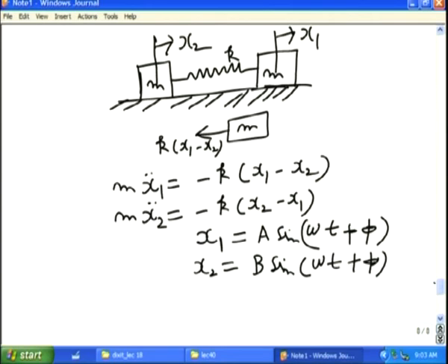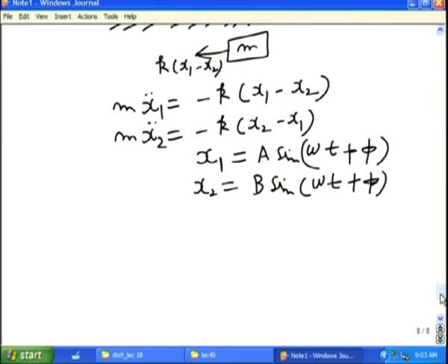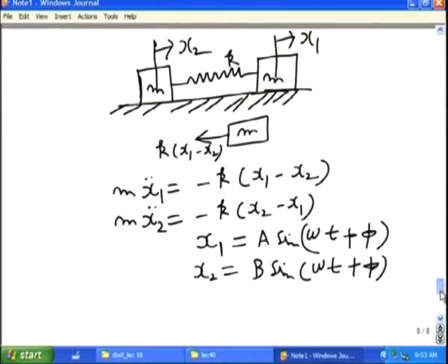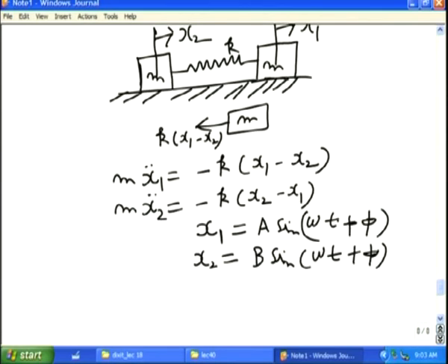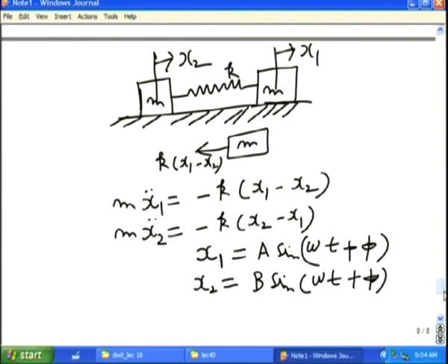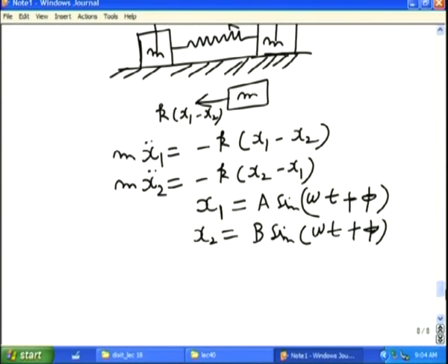So, essentially by solving the differential equations, you can study the vibration. In this problem, there will be two values of omega which will provide the solutions, and these will be called two natural frequencies. So, in a multi-degree freedom system, if there are n degrees of freedom, then you will get n equations. Therefore, the concept taught here can be easily extended to the multi-degree freedom system. Okay.